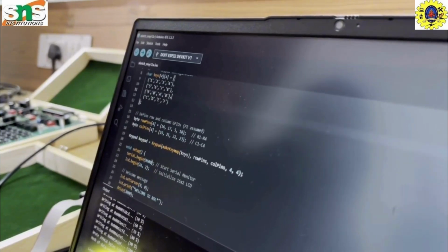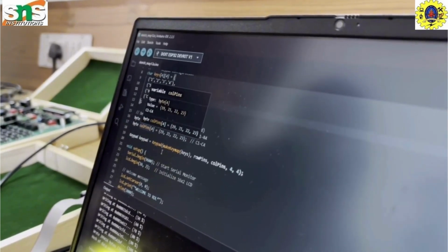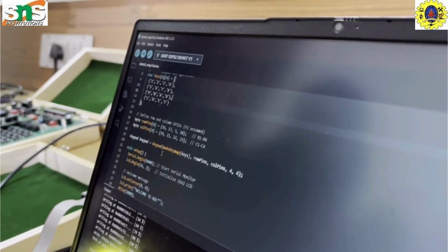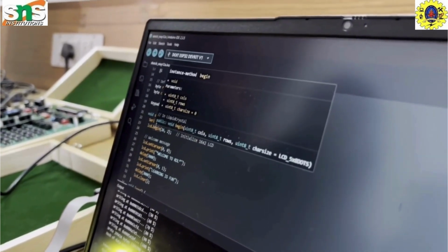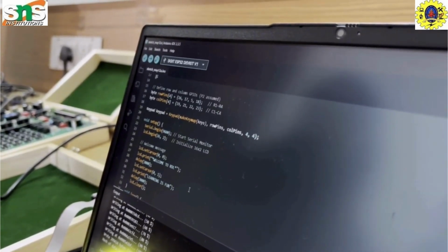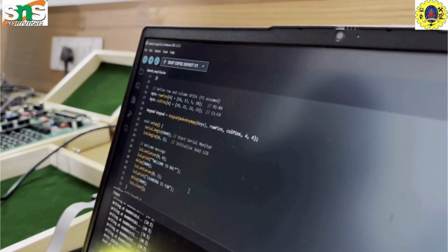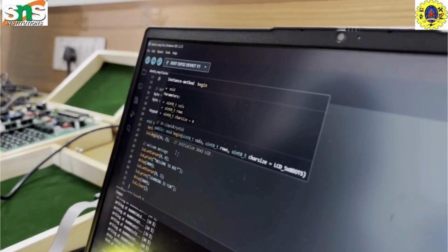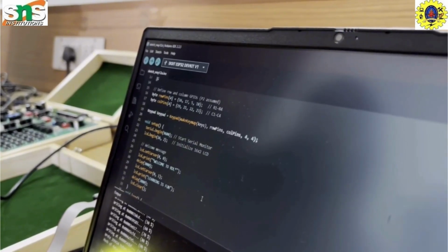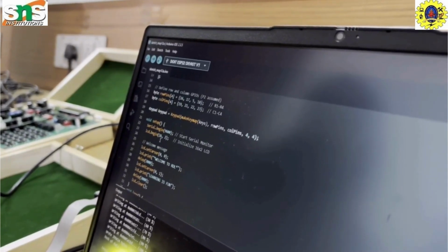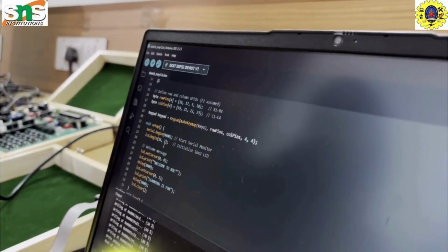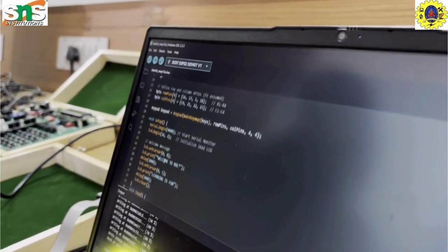Now I am defining whether it is an int, float or byte, like that. And now I am calling the main function. In the main function I have to see my output in both the serial monitor and also on my LCD screen. So I am calling serial to begin at the 9600 baud rate and the LCD to begin at 16x2. So I am giving the configuration as 16x2. And now the welcome message.